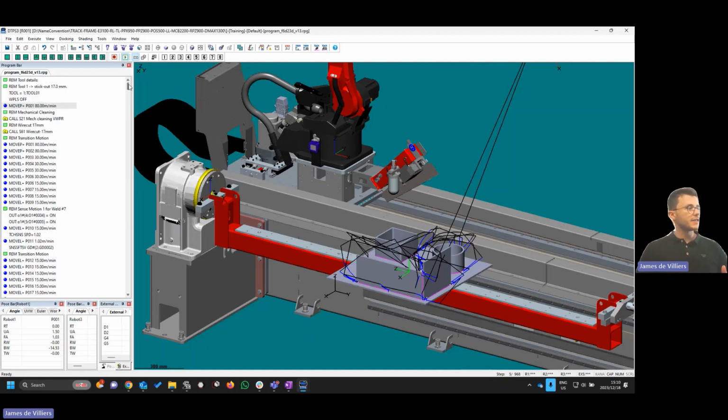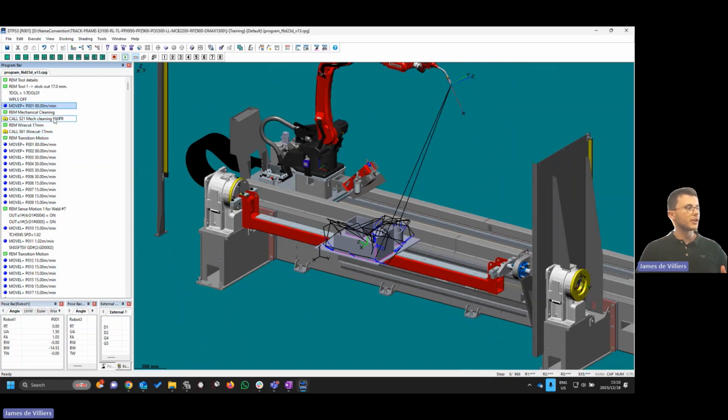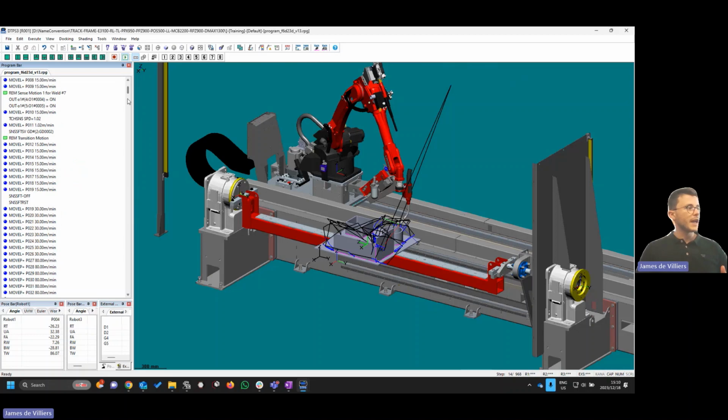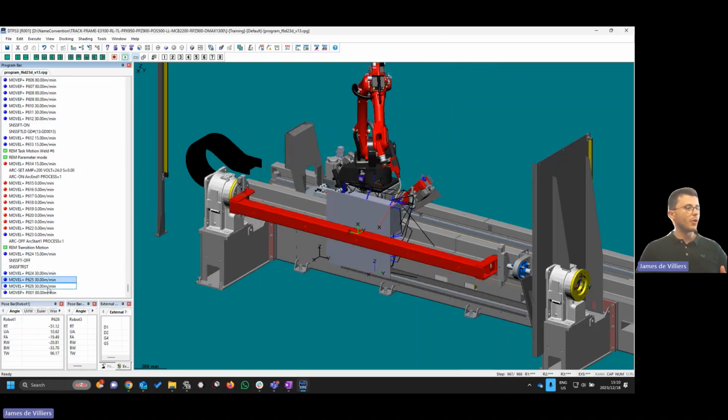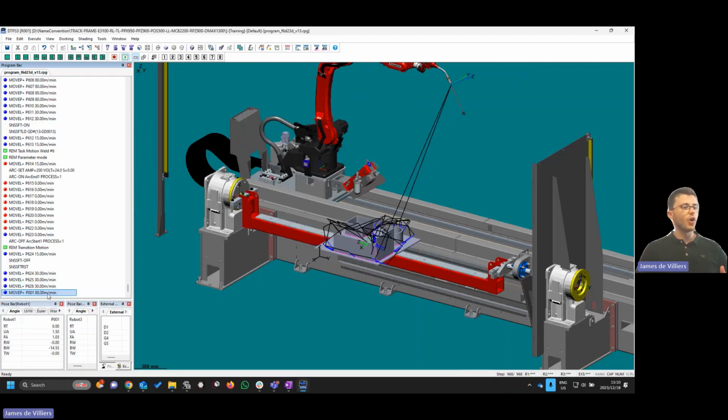Now you can see in the program on the left, we've created quite a lengthy program inside here, and everything is inside there for you. So we've got mechanical cleaning called, we've got the wire cut called, it's at the home position first, cut, it's going to clean, cut, and then go after the program. And at the end, you'll see the program also takes everything home right at the end. This is now completely collision free. As long as everything's defined perfectly, it's basically ready to go.